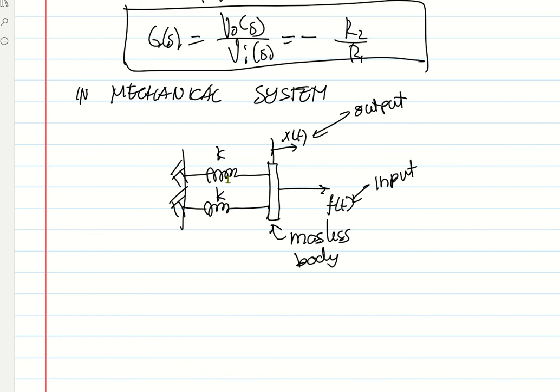Remember in physics, if two springs are in parallel, we can simplify them into just one, just like resistors in parallel or inductors in parallel. That equivalent will be just the sum of the two. And k plus k is just equal to 2k. So the equivalent spring constant of the two will be twice k.